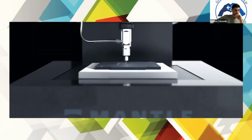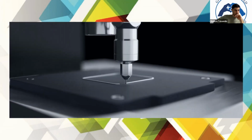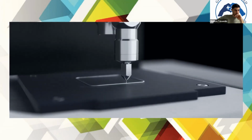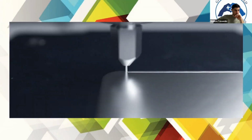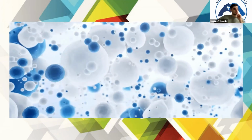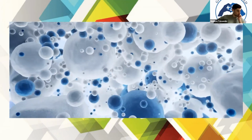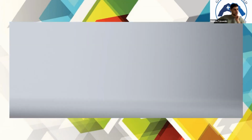At its core, TrueShape is an extrusion process. Using a precise positioning system, paste is deposited one layer at a time. Once an entire layer has been printed, it is heated to remove the liquid components of the paste, settling the metal particles into a dry, dense compact, which is held together by a small amount of binder.